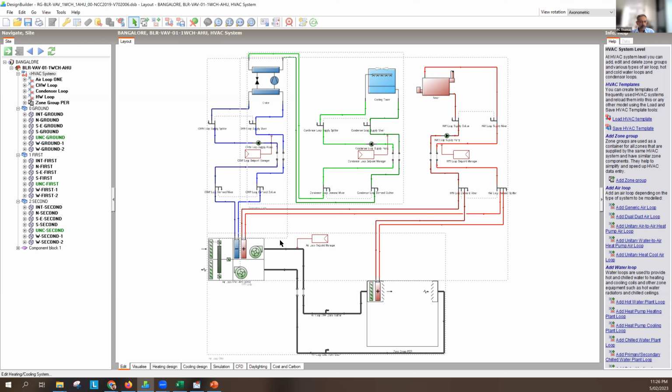Your cooling load doesn't change. Your total cooling load is the same. If you've got a building for which you've got a particular kind of operation, for which you've got a particular kind of materials, U values, different kinds of windows, lots of roof insulation, there's one cooling load for it, your maximum cooling load, which has been calculated when you did your load calculations. But how do you go about trying to address this load in an efficient way. Okay.